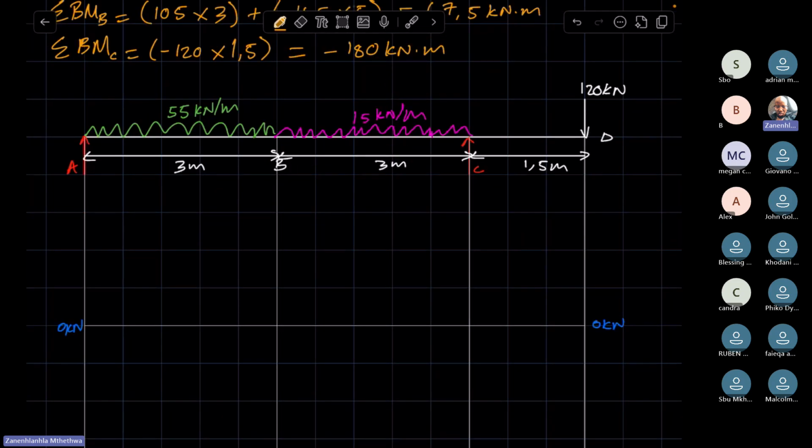Where you have critical points, you draw a section on the right-hand side of each of those points. So you're going to have a section on the right of that point, a section on the right of this point, a section on the right of that one, and a section on the right of that point.